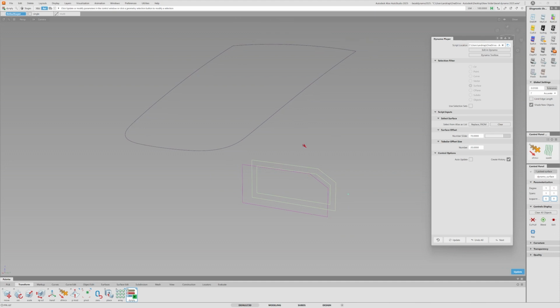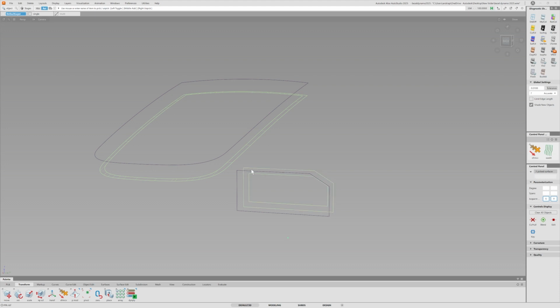And we can also do it for this surface here. So select this surface, offset down 70 with a tubular round of 20. Say build. It takes a little longer, it's a little more complicated, and there you go. So just one surface, offset at 70 with a constant tubular offset of 20. Okay, so if I delete that, how is that going to work with multiple surfaces?